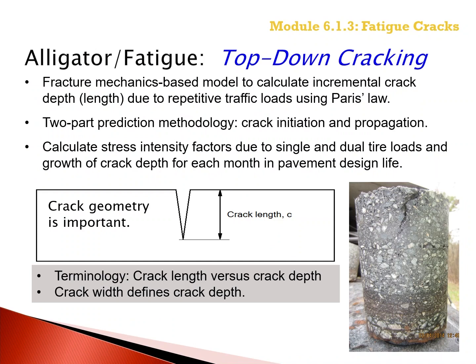A fracture mechanics based model or approach is used to calculate the incremental growth in crack depth, and crack depth is sometimes referred to as crack length, due to repetitive traffic loadings using the Paris law.